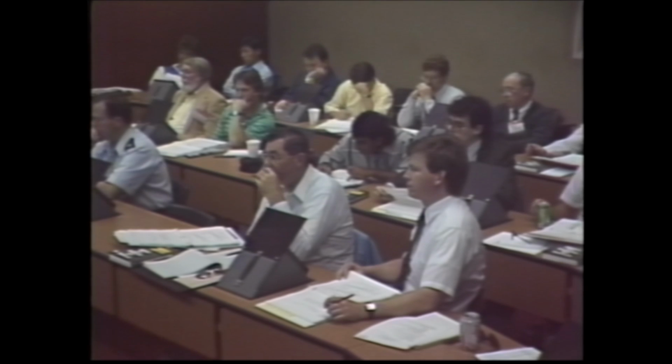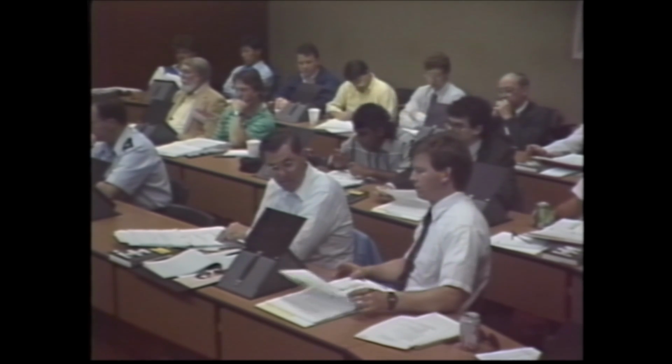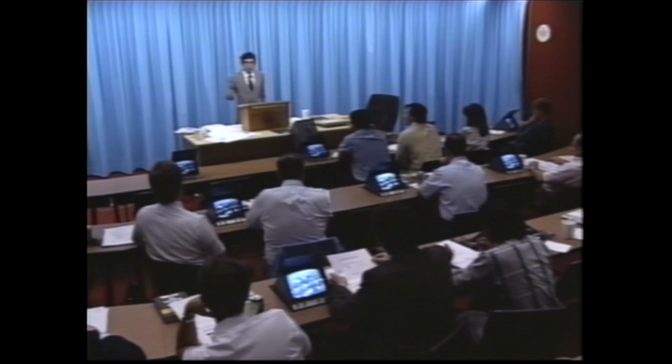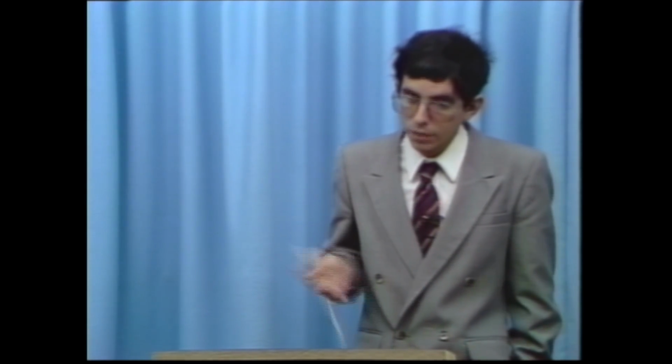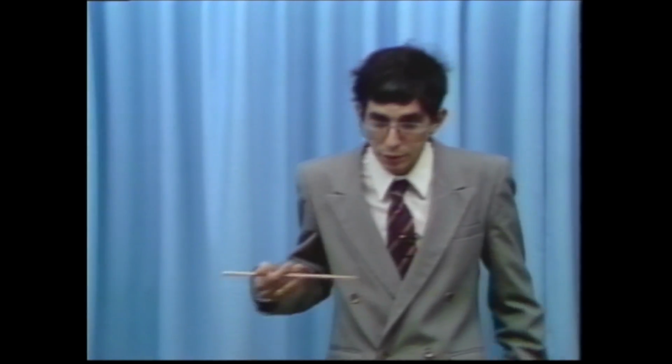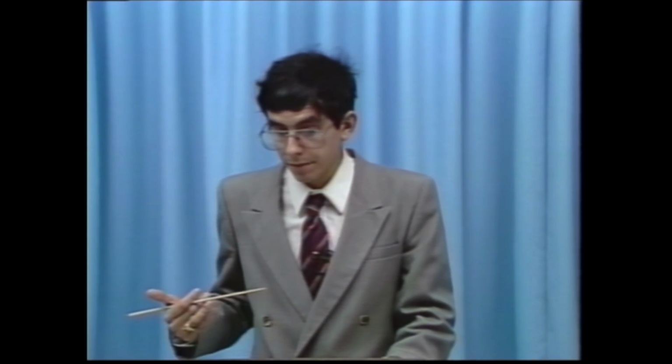Now, what's one of the first questions you ask about a boundary layer? I mean, those experts in boundary layer, I say, hey, I've got a boundary layer on the vehicle. First question you're going to ask is, well, is it laminar or is it turbulent? Because the whole nature of the boundary layer depends on whether it's laminar or turbulent. And you know that for low-speed applications, we have pretty good ways of estimating when the flow will transition from laminar to turbulent. So they're semi-empirical, but by and large, we have a pretty good feel for when that occurs. One of the first problems we run into in hypersonic flow is we don't know the answer to when the flow transitions. Let me show you a plot of transition.